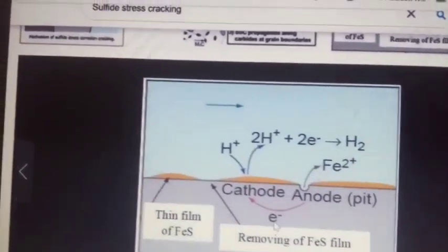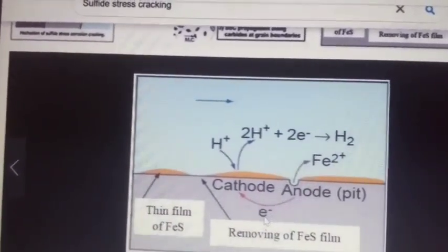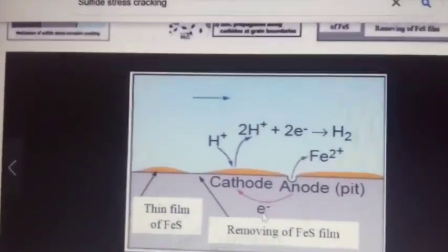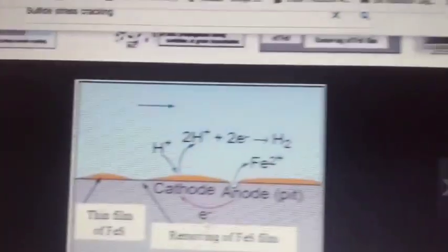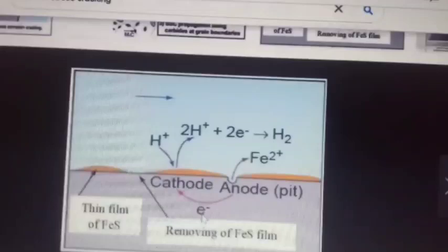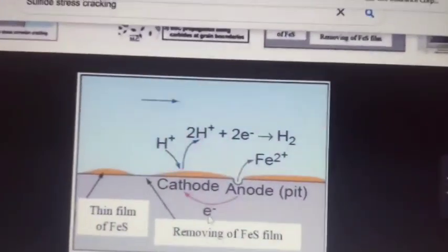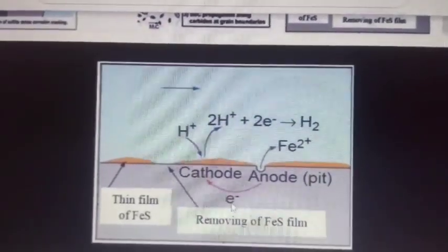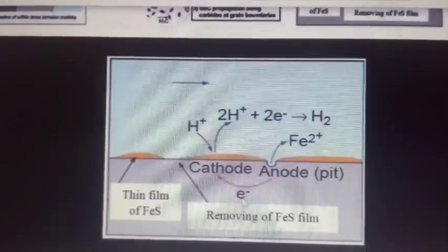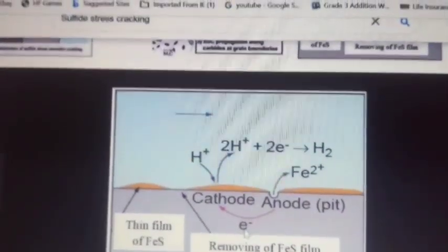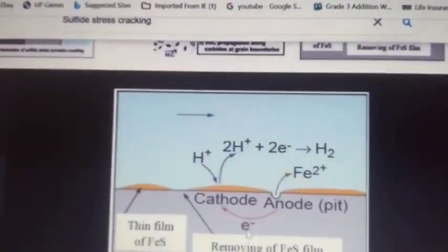Whereas in CRA, that is any austenitic stainless steel, where an austenitic phase, FCC, face centered cubic, is present, the gap between the atoms is 0.52 Angstrom. The monoatomic hydrogen is 0.49, so it is completely soluble.